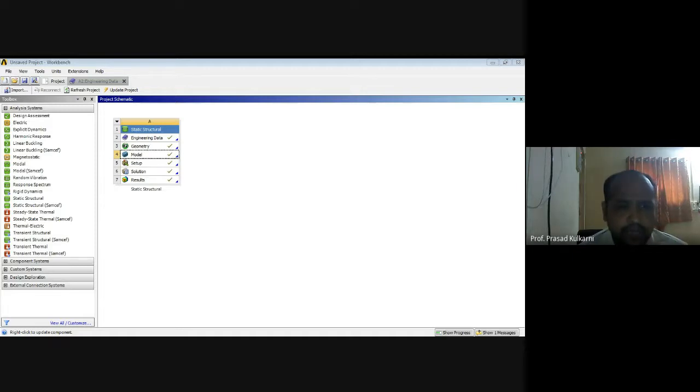At the same time you can find the factor of safety over here. Here is the stress tool tab. I will click on the stress tool, then I will click on the safety factor and here you can see the maximum is 15. So this is an analysis using elastic properties. Only Young's modulus is taken into consideration. If you want to go for the non-linear analysis, then you have to use the stress versus strain chart, which we will see in the next session.